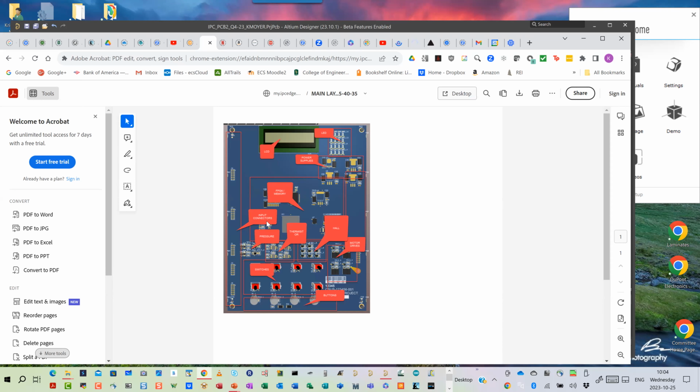I want to see how you as board designers think through the various different challenges, the types of parts, the type of structures, and so on, what you would put where. The main thing is we want input connectors on the left, output connectors on the right, motor drives on the lower right, buttons and toggle switches bottom middle, push buttons themselves at the very bottom edge, digital in the middle right here where we have the processor or the FPGA, memory, and so on. We roughly want the LEDs in the upper left corner and the LCD top center.